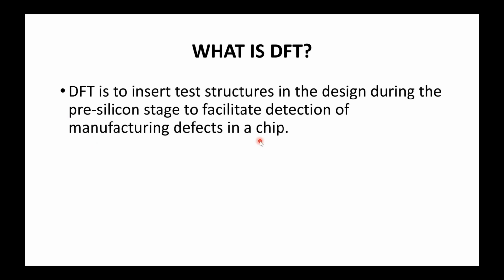If a particular chip fails after manufacturing, we will be able to tell what manufacturing defect has caused the chip to fail. So this is what DFT is. DFT is to insert test structures in the design, done during the pre-silicon stage to facilitate the detection of manufacturing defects in the chip.